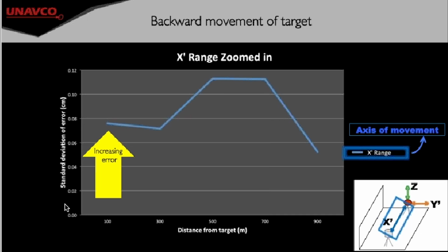Rather than having to deal with the spot size and the mirror calibration and how the scanner turns, which affects both the X and the Z coordinates, it is only dependent upon the light leaving the scanner, hitting the target, and returning.